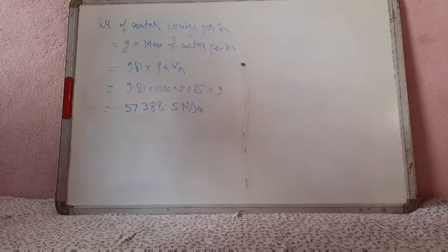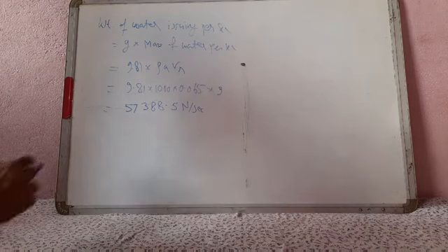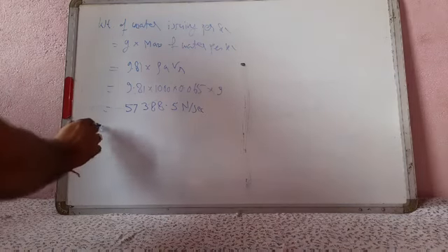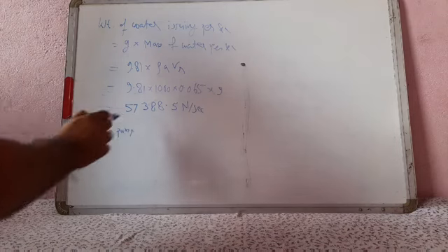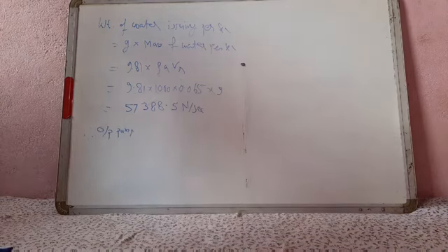The pump should have the output which will give the jet a relative velocity VR and also overcome the pipe losses. Pipe losses are the friction losses, so we have to consider all these. So the output of the pump per unit weight of water should be more than the effective use, to overcome the pipe losses.